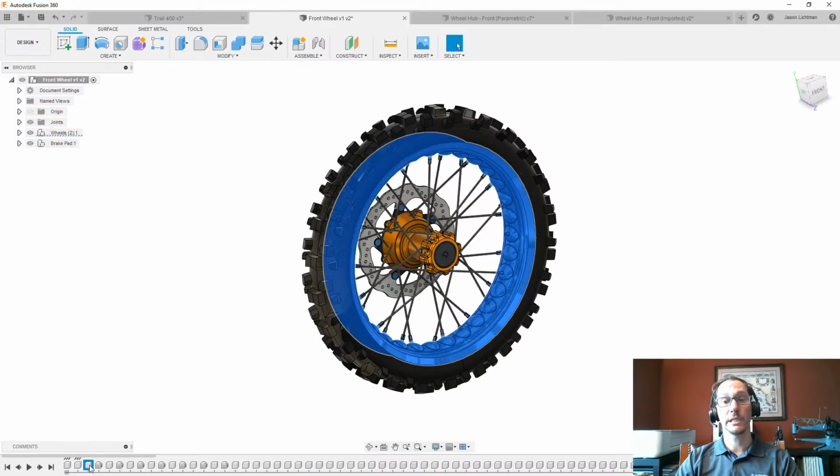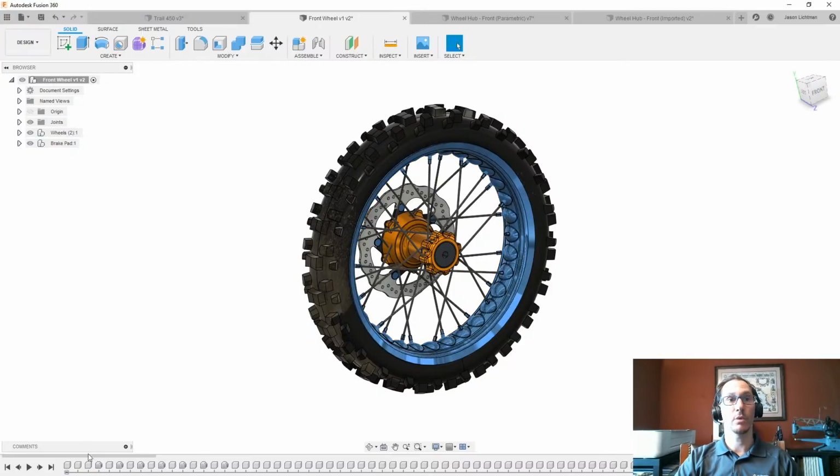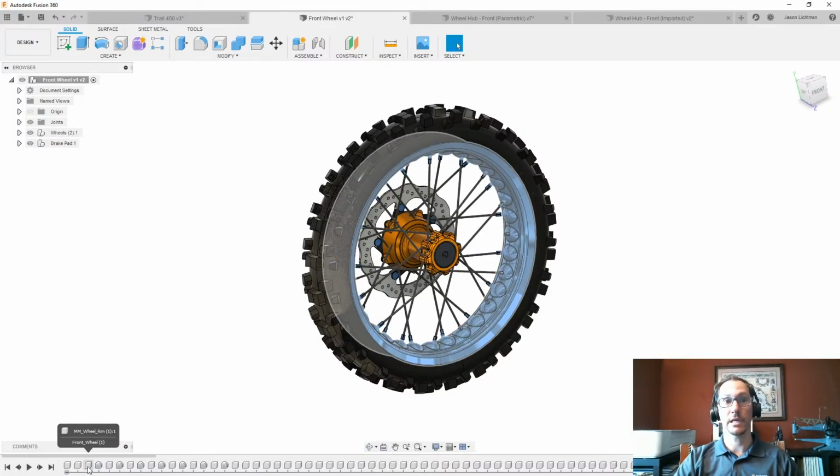And if any of you haven't seen those before, this icon means that it's a creation of a component. So every time you create a component, like that hierarchy where you have an assembly and then a subcomponent, then another component under it, or a subassembly, all of those different levels, every time there's a different level, you'll get one of these white icons that says this is creating a new component. There's no geometry in there. It's just saying this is creating the hierarchy. So for the geometry, it actually brings in that base feature.